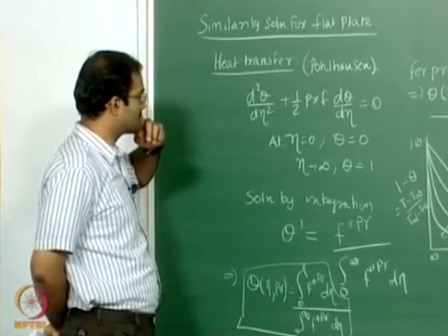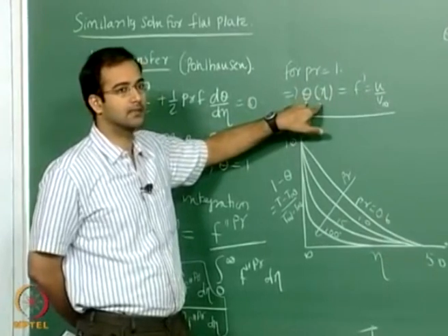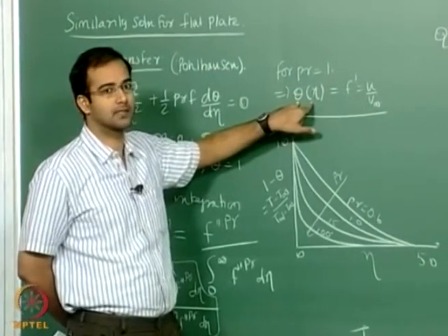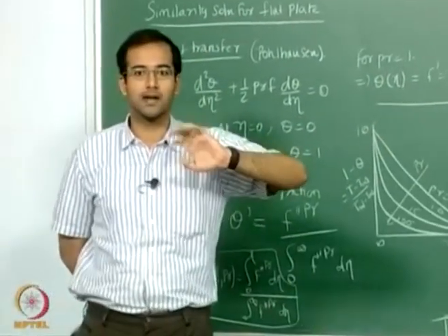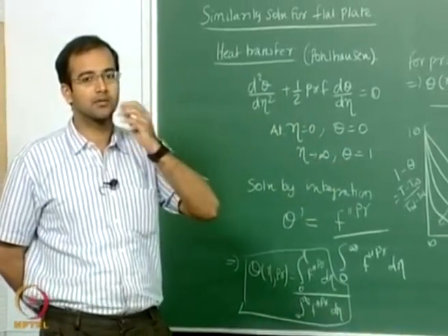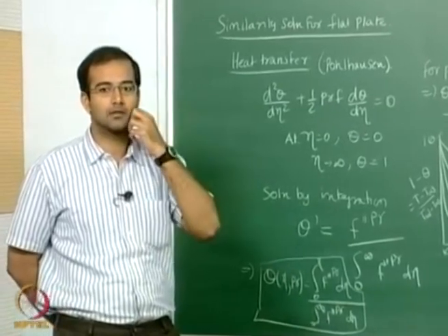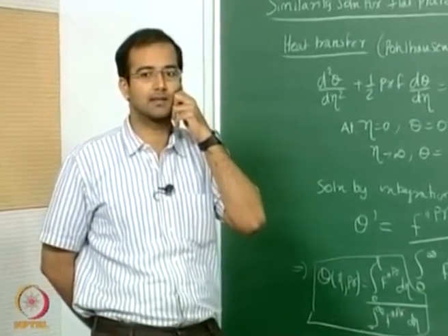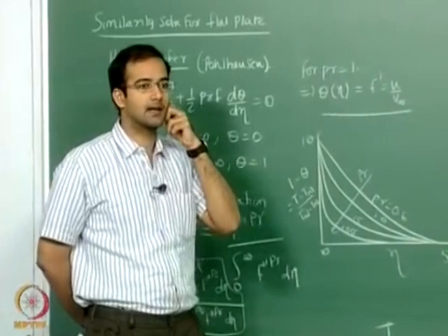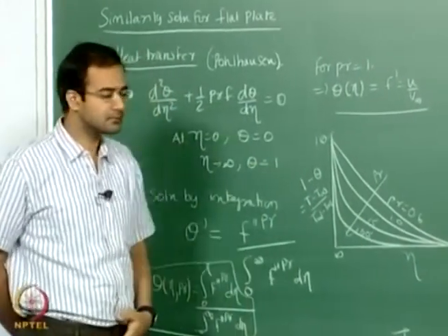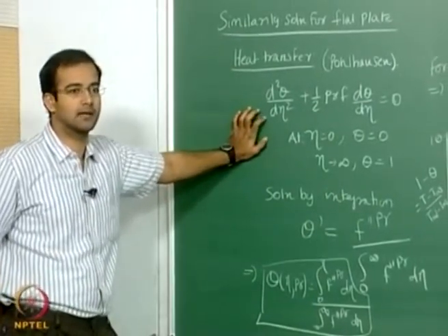And of course, you know, from the intuition that for Prandtl number equal to 1, if you replace the temperature variable, non-dimensional temperature theta, with the non-dimensional velocity, the momentum and the temperature equations are identical exactly. So Pohlhausen got the idea that if for Prandtl number equal to 1 they have the same solution, then for other Prandtl numbers there should be some kind of a similarity solution possible. So then he intuitively substituted the same similarity variable which was used for the velocity boundary layer, and finally he finds that this falls into the category of similarity solutions.